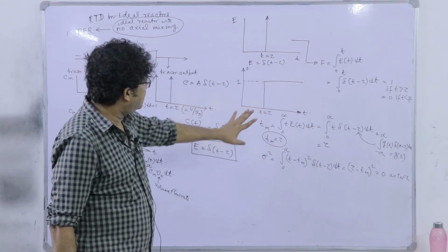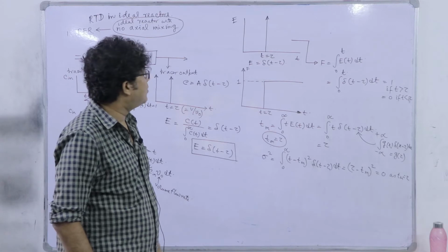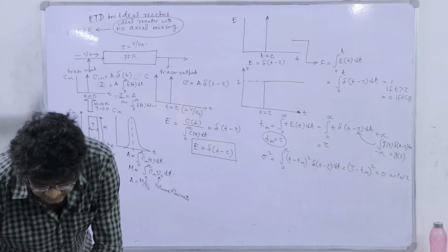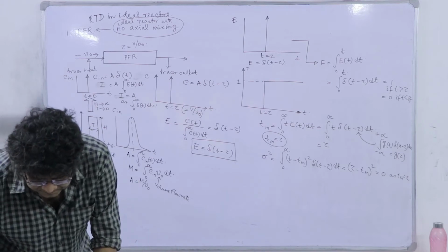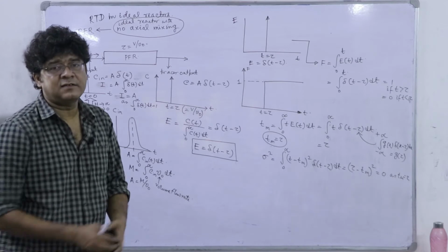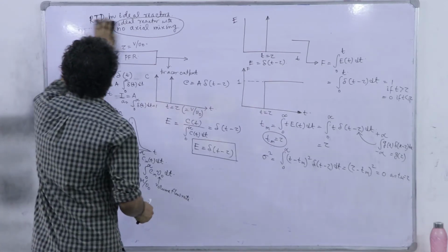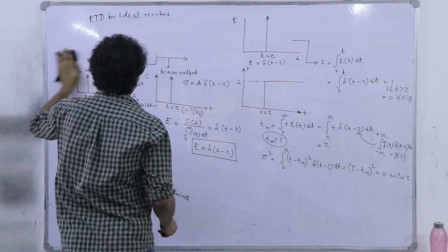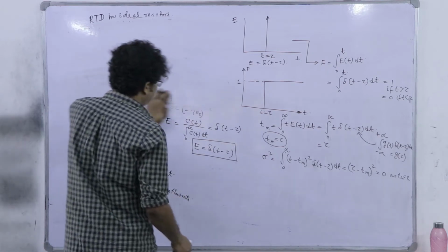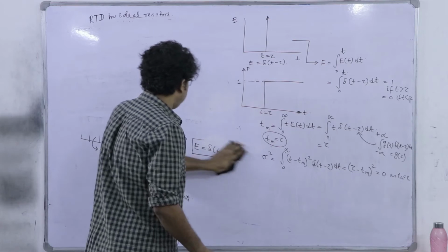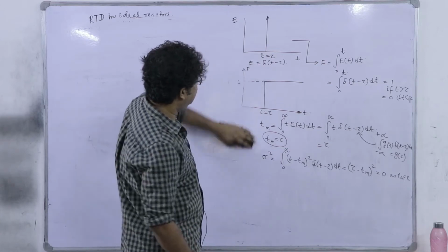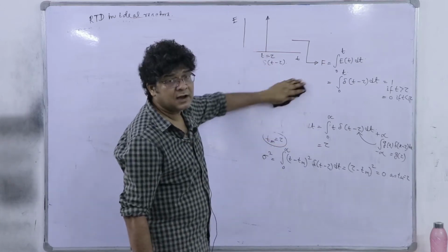So that is about the single PFR without any dead time or bypass. We have the E curve and we have the F curve. Now we will think of a PFR with channeling, that means it has a bypass and the bypass line has 0 residence time. The PFR bypass line is theoretically considered. These are all theoretical analyses, never happening in reality because we cannot actually construct a PFR.